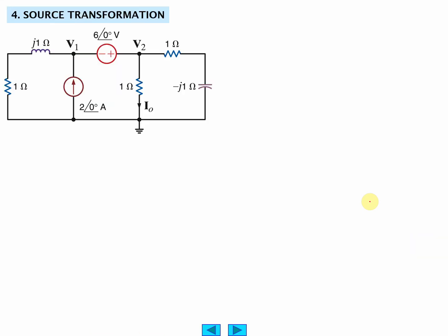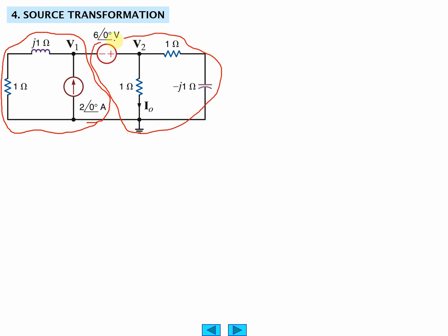Thevenins and Nortons again. Source transformation. This just does that. You can replace, I'm going to outline it again. I'm not going to actually do it. Say you can replace this with a Thevenin's equivalent, and you can replace this with a Thevenin's equivalent, and you can convert a current source to a voltage source, so you have a couple voltage sources and resistors. Or maybe it'd be better to have a couple of current sources that are hooked together. You'll notice a couple of current sources and resistors.